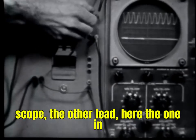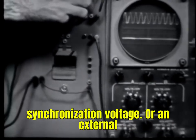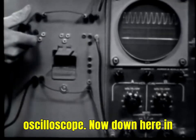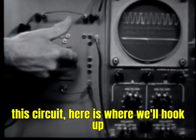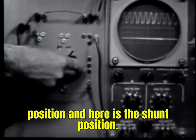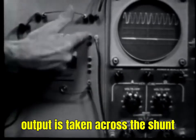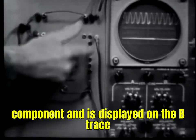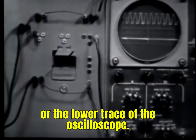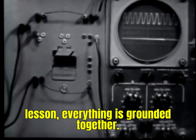The other lead here, the one in the middle, is used to provide a synchronization voltage or an external trigger for the sweep circuits of the oscilloscope. Now, down here, in this circuit here, is where we'll hook up our filter components. This is the series position, and here is the shunt position. Now notice, as is always the case, the output is taken across the shunt component and is displayed on the B trace or the lower trace of the oscilloscope. Note also that, as we did in the first lesson, everything is grounded together.